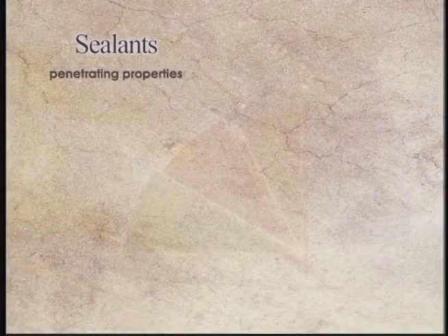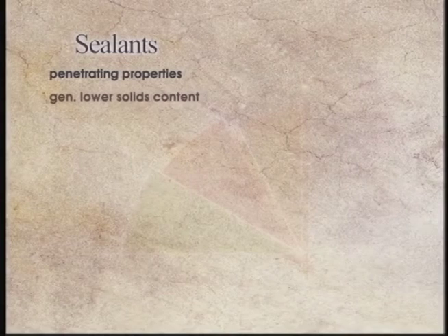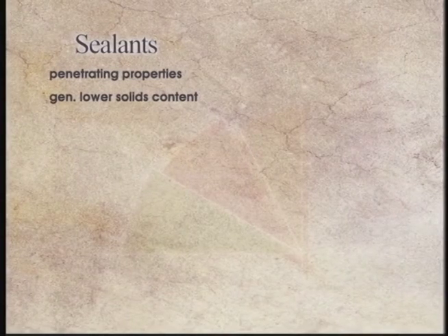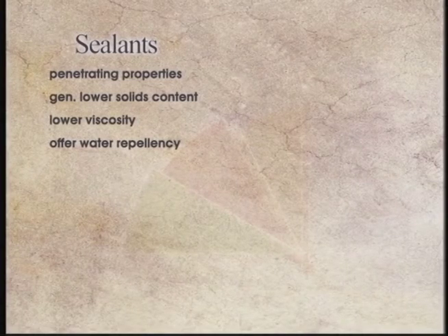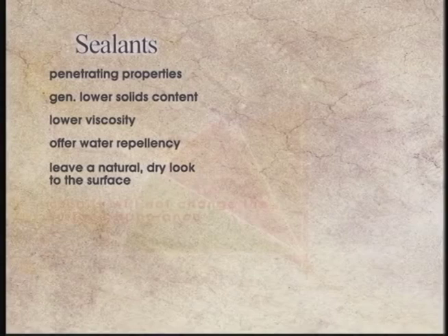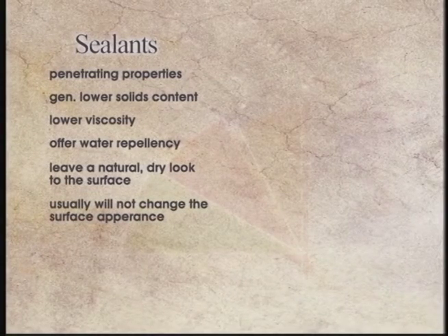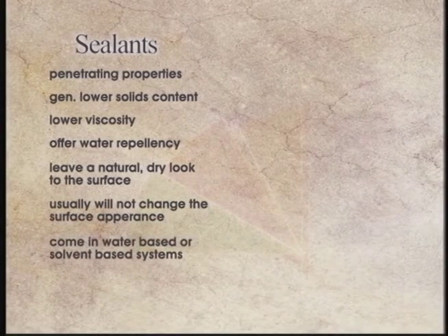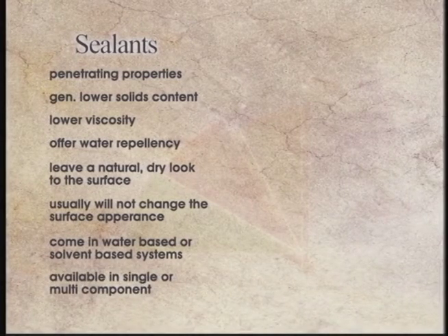Sealants. Penetrating properties. Generally lower solids content. Lower viscosity. Offer water repellency. Leave a natural dry look to the surface. Usually will not change the surface appearance. Come in water-based or solvent-based systems. Available in single or multi-components.